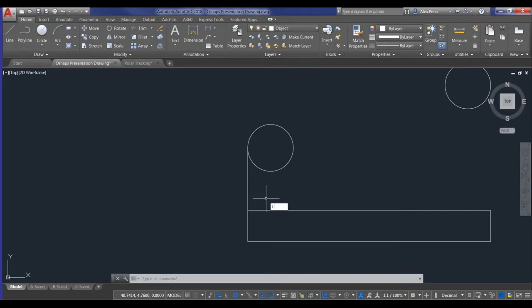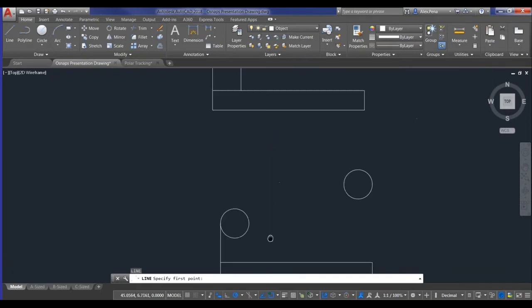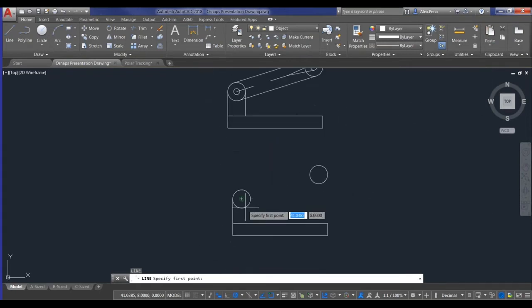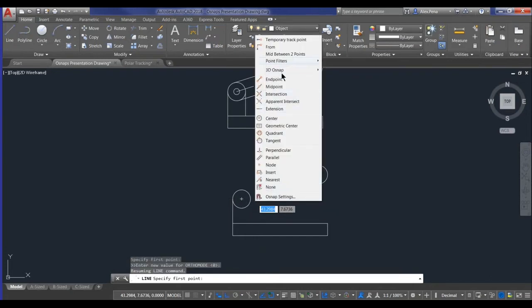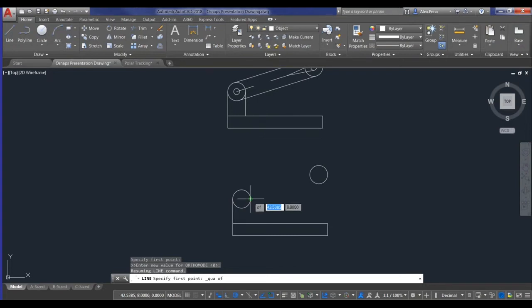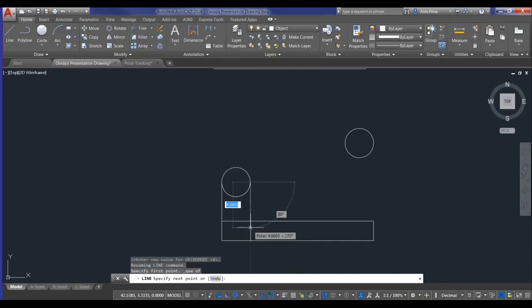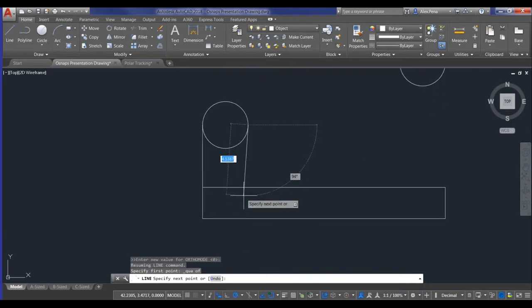So I'll activate the line command again, to make this next quadrant line down, as shown in the model above, and I run into the same issue where the center snap is overriding. I'll Shift right click again, and this time I'll choose the quadrant again. When I go down here, though, you're going to notice that I can't connect to this line here. There's nothing that I can do. I can try to append from this one, but then again that'd be too much work.